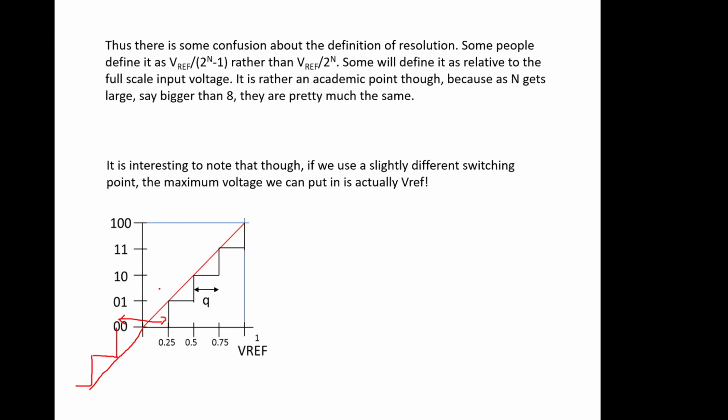And what you end up then with is a double width dead zone at 0. Whereas if you move the staircase over to the left a bit, and this one over to the left a bit, you get an equal system. So if you're going positive and minus on your A to D converter, it becomes important. If you're just going positive, then you have the option to move this decision staircase over a bit. Or what I should say is pick a converter that has that decision staircase in that position, because it's not something you can change at a whim. You've got to pick the right one.